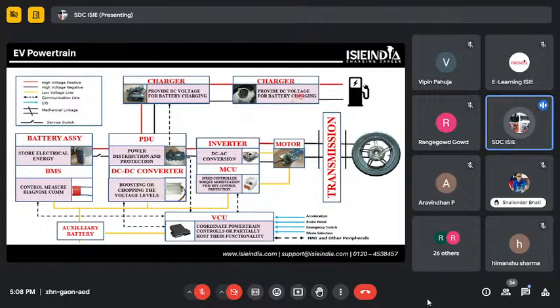It's going to support DC fast chargers, AC chargers, level 2 chargers, or level 3 chargers. As per that, bi-directional power flow should be there, and they also have CAN communication signals. From here you can see the dotted line indicates the communication line. With the integration, we make an interface connection with a charging station, and we also have a communication channel through the charger to the EV charging stations, where we can analyze the condition of the battery.